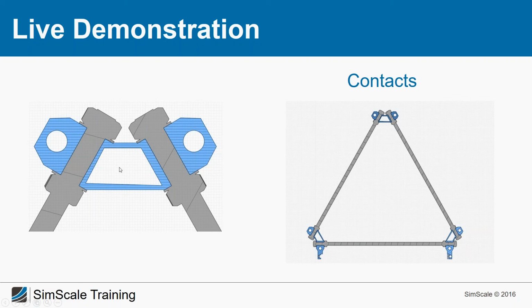And if we take a look here, we have first of all a contact between the inner surfaces of this connector and the outer surface of the rod. We have the same on the other side. And if you think about it, it seems to be defined, so we cannot tilt it, but we could still move it along this axis. And therefore we need a third contact, which is connecting the lower surfaces of the nuts to the surface of this connector.